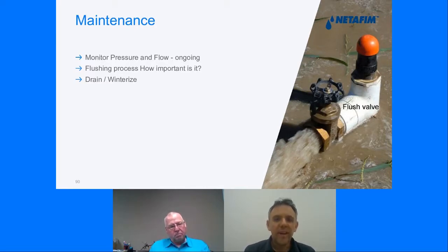Question from Brazil, from Carlos: What is the usual length of the lateral lines? There are multiple sizes of drip lines that we use. We use a 636, an 875, and a 990. With the 636, we can typically go about 600 to 700 feet, depending on the dripper flow and the spacing. With the 875, we can typically go 1300 to 1400 feet. And with the 990, we can typically go up to 2600 feet.